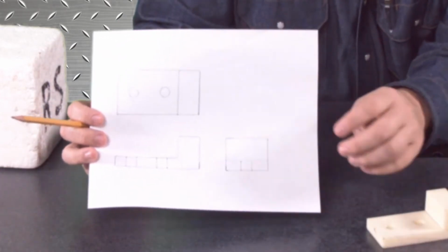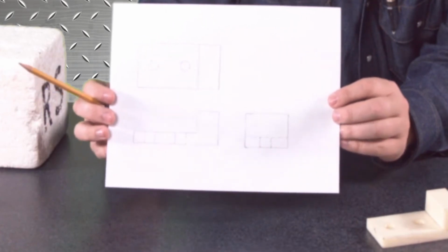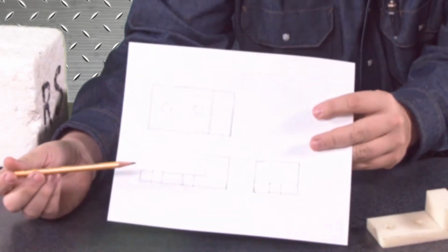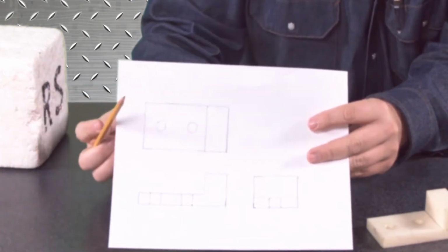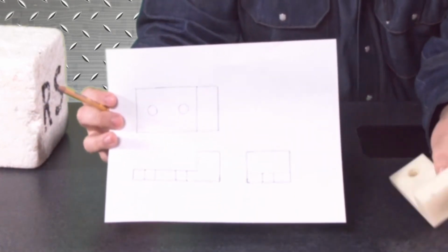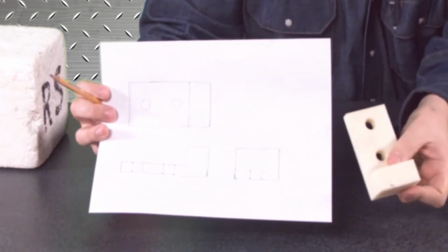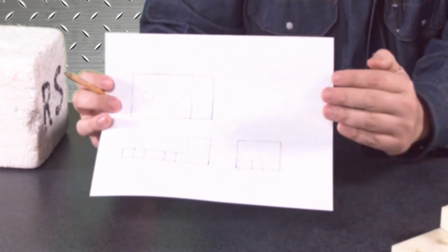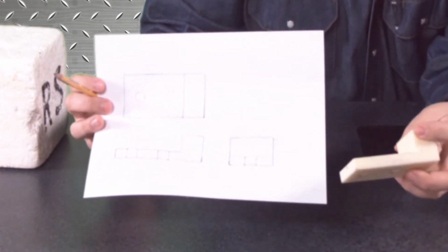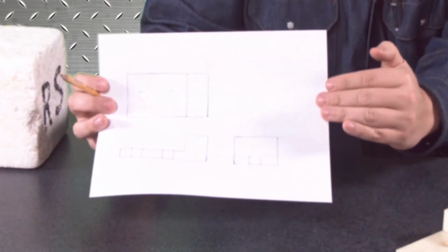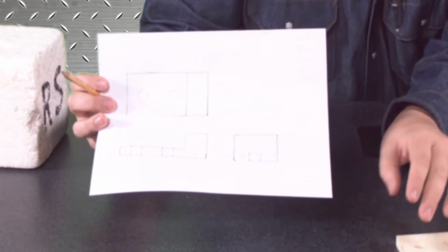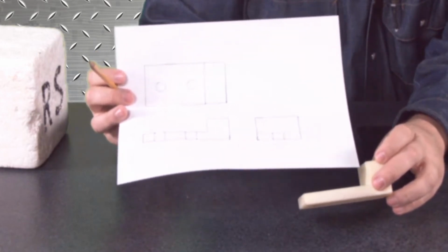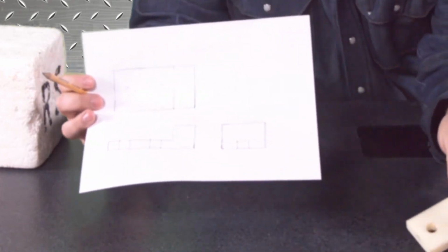So whenever you see a print like this, you can know what the object is going to look like based off of these three views. You could go out there and either machine a part like this, or weld together a part like this and fabricate it, and you'd know what it needs to look like in real life based off of these three views, because they are the ones essential to know where the holes are, where the points are for these planes, and the orientation of it itself.